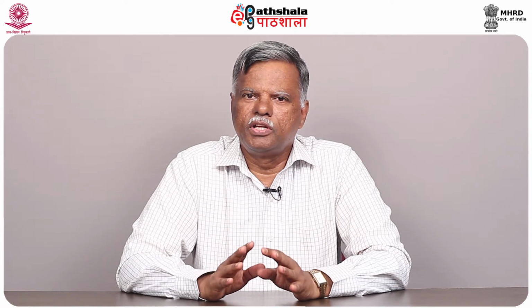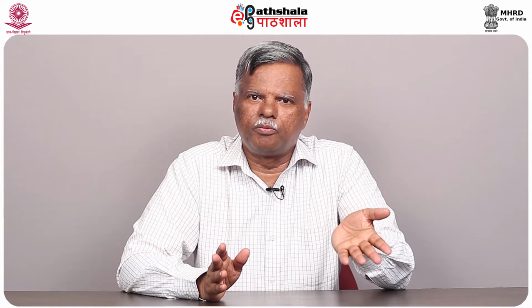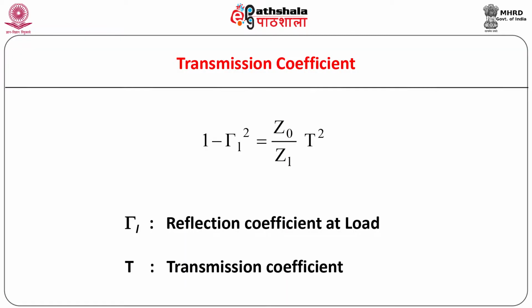The two coefficients are obviously related with each other because the net power consists of the sum of the reflected power and the transmitted power. So, these two results are very important as far as transmission lines are concerned. Both the coefficients, namely reflection coefficient and transmission coefficient, are complex numbers, as I just mentioned, having individual magnitudes and phases, and can be shown to be related to each other through the relation as shown. Let us see how the relation between them can be derived.